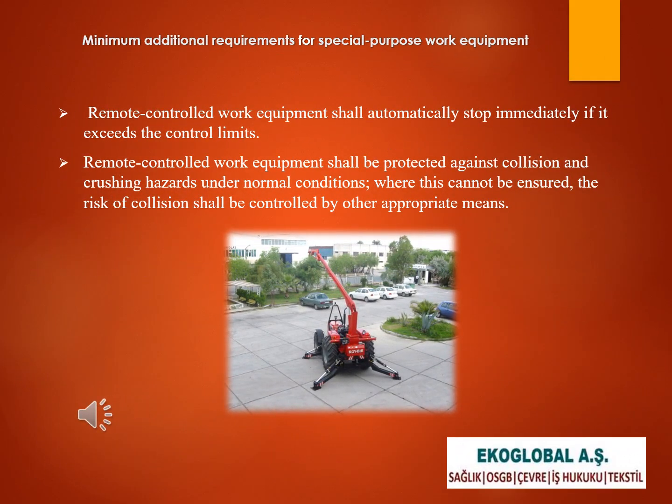Remote-controlled work equipment shall automatically stop immediately if it exceeds the control limits. Remote-controlled work equipment shall be protected against collision and crushing hazards under normal conditions. Where this cannot be ensured, the risk of collision shall be controlled by other appropriate means.